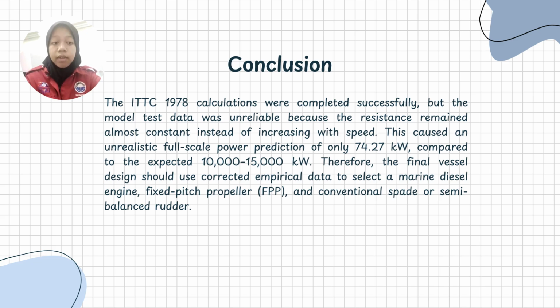10,000 to 50,000 kilowatts. Therefore, the final design should use corrected empirical data to select a marine diesel engine and fixed pitch propeller (FPP) and conventional or semi-balanced rudder.